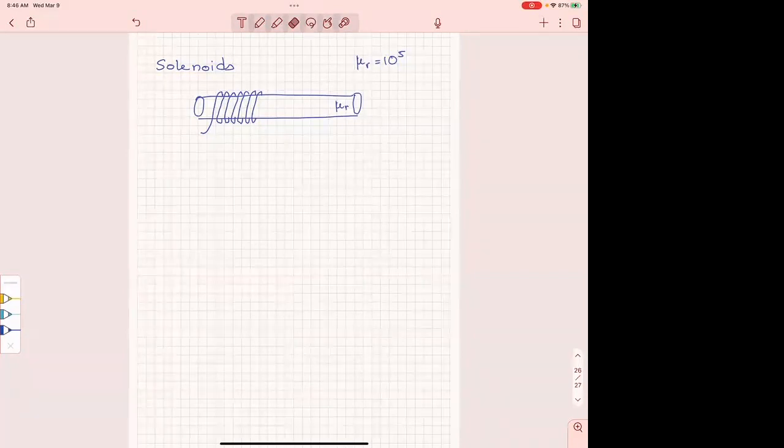And all of those may look like this, all the way up until the end, and they may be 100, 200, 1,000, depending on how much inductance you want. Now, if you have a case like this where n is very large, it could be even 50, all right? When you have a case where your loops are so many and so close, the magnetic flux in there is not exactly the same as the magnetic flux we have calculated for multiple loops that may be separated.